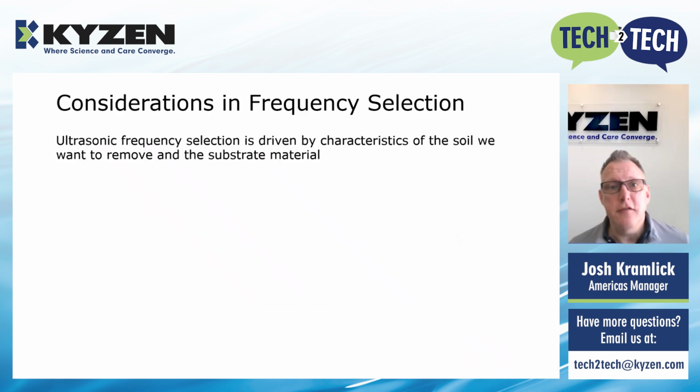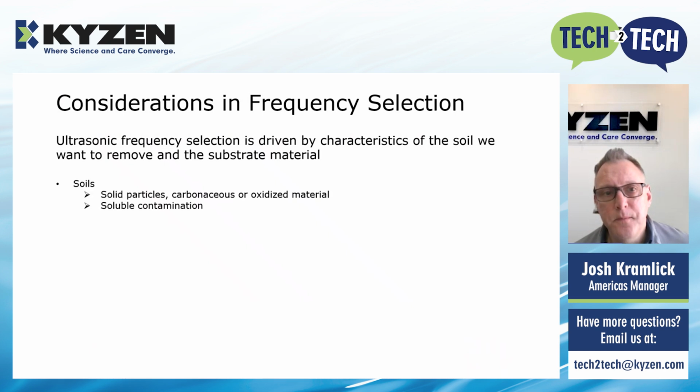Considerations in frequency selection. Ultrasonic frequency selection, much like chemistry selection, is going to be driven by the characteristics of the soil we want to remove and the substrate materials themselves. The examples of soils could be, again, solid particles or carbonaceous or oxidized materials that are very tenaciously adhered to the surface. Or we could simply be looking at soluble contamination.